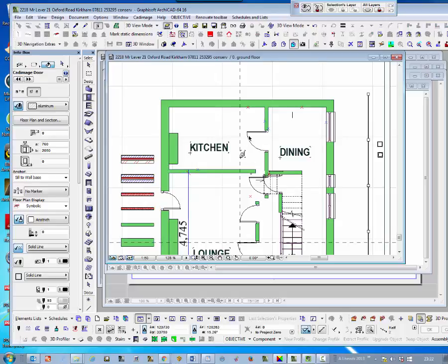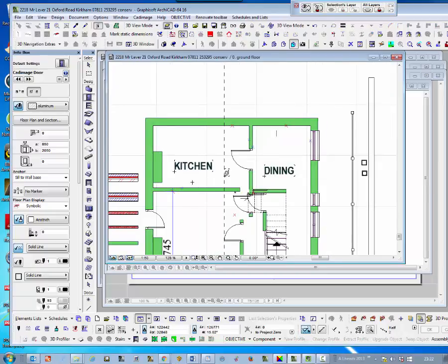Okay, now then, we need to form an opening in this wall here. So we use the door tool and we Alt click on the door, and we are going to place a door, and my survey notes are telling me that it's 670 from that corner. So in the corner, X 670 plus, because it's in that direction, and that's where the door is.